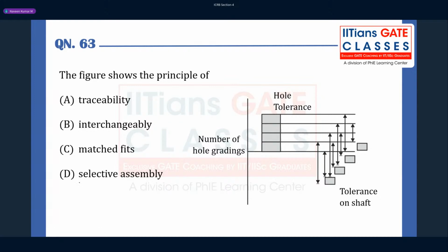This will talk about selective assembly. What is selective assembly? You sort them first. Here, see, sorting has happened. Properly sorting has happened. You sort them first, and then you take one by one and see which has the closer tolerance according to the part diagram they are given. Because in assembly only you will see all this tolerance, because it has to fit. Somebody has designed, somebody has manufactured. Assembly people have to go and fit it. If it is not fitting, either it is a mistake of the designer or of the manufacturing person who has done it. Right?